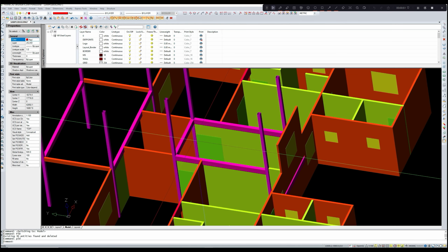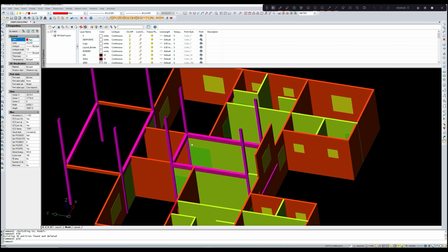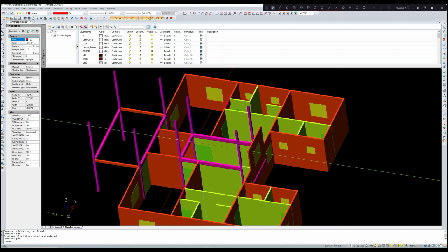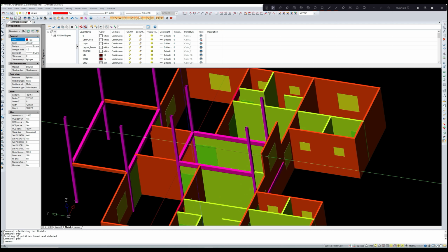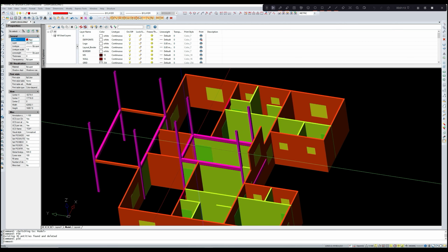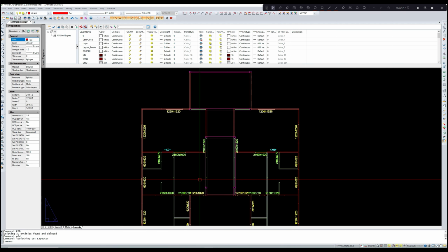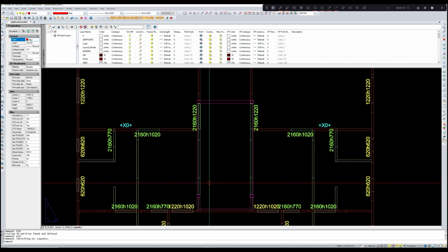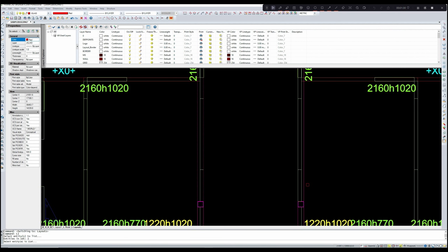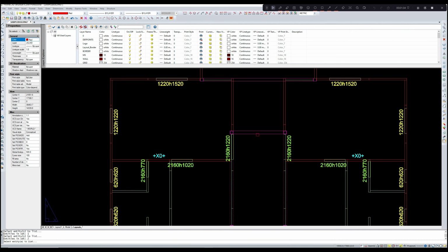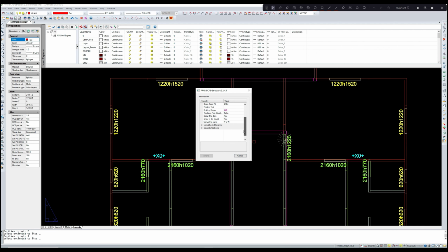Now this joist depth actually, before deciding the joist depth, we should make a panel having greater span and test whether the joist is passing or not. So this has been already tested with 1.15 mm thick, the joist passes, but we'll start with a joist with 0.95 mm thick stud. Now let us go back to the layout. In the layout, we'll correct the elevation height, the top reduced level of this beam. So list this beam, list command, select this beam and this beam. So the beam top RL should be 3050 plus 350, that is 3400 mm.